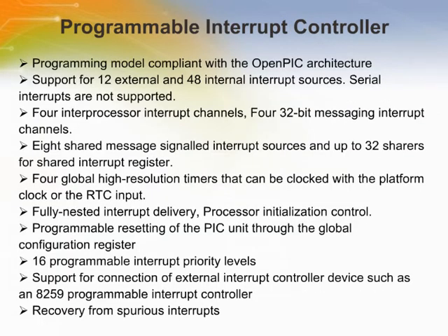The PIC prioritizes and manages interrupts directed to the INT signal. It also manages the interrupts generated by the PIC itself and by off-chip interrupt sources. The PIC is compliant with the Open PIC architecture. The interrupt controller provides interrupt management and is responsible for receiving hardware-generated interrupts from different sources, prioritizing them, and delivering them to the CPU for servicing.